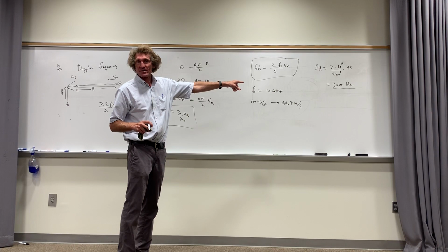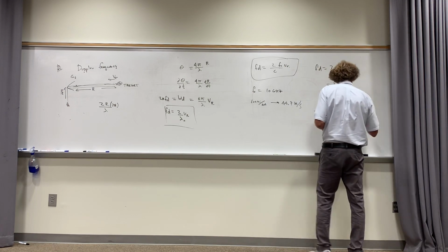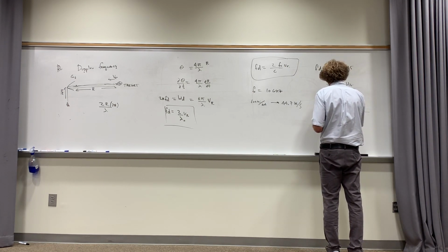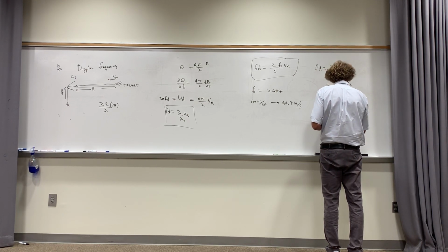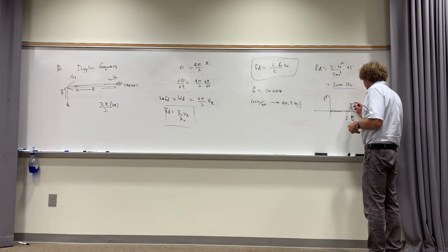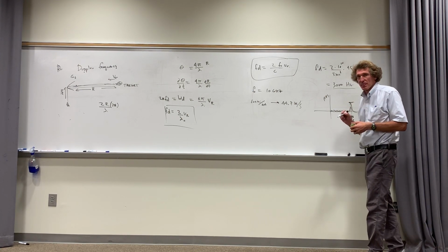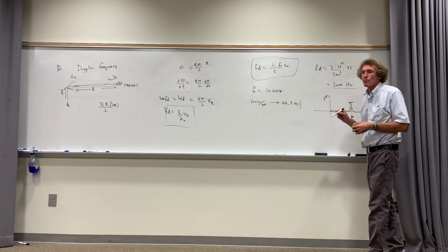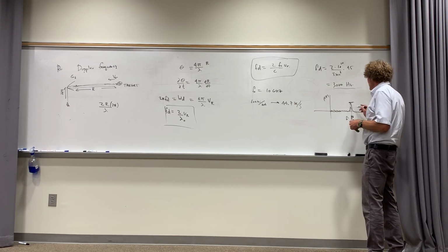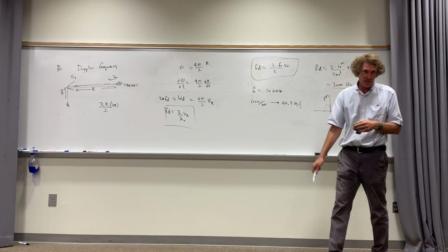And that's later on. Anyway, that's not a lot, is what I'm saying. If you look at an actual signal in a spectrum analyzer, with power density versus frequency, you're going to get a threshold, and then you're going to see a crisp little peak at your operational frequency F0. Now, if that shifts of the order of maybe 5%, you can notice the shift. But you can't notice a shift if it's 0.0001%. The only way you do that is move all this down to where it's now at 0 frequency. Now we can see the shift, and that's what we do.